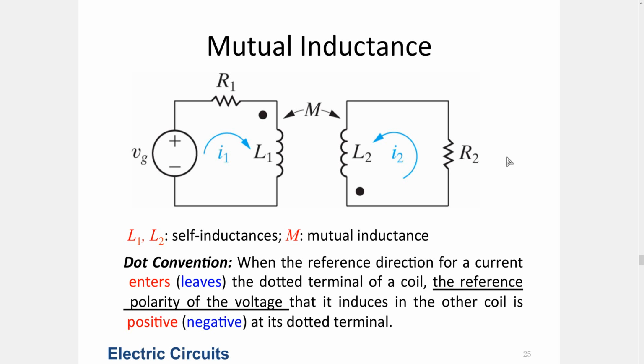Normally, each inductance will have some self-inductance. That is what we have defined so far. And we can have some coupling between these inductors. It's defined by K, typically a number between 0 and 1. And the mutual inductance is defined as K times the square root of L1 times L2. Okay. So if the inductances are very closely coupled, you will have large K values. If they are far away, they will have smaller K values. They will affect each other loosely.